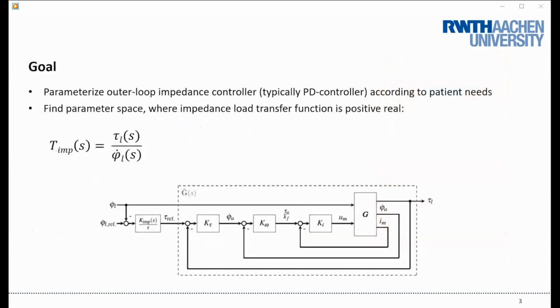So our goal of this research was to parameterize outer loop impedance controllers such that the impedance load transfer function has the positive real property. This ensures stability with uncertain and nonlinear passive patient dynamics. However, note that we developed in the following a procedure for the general case.